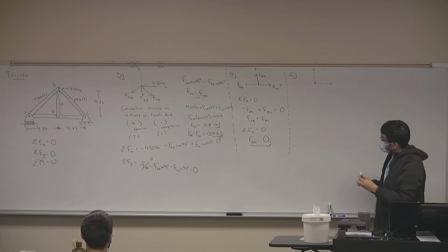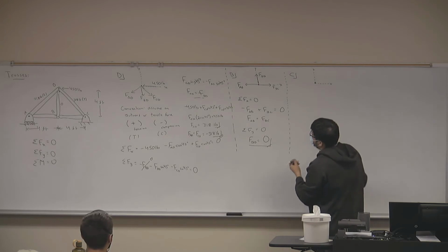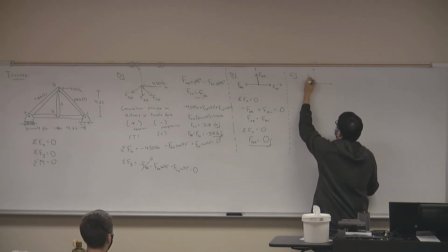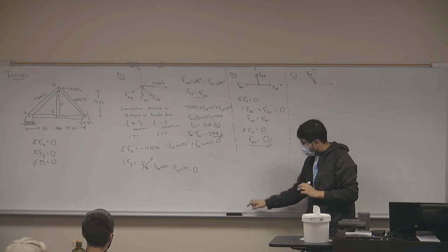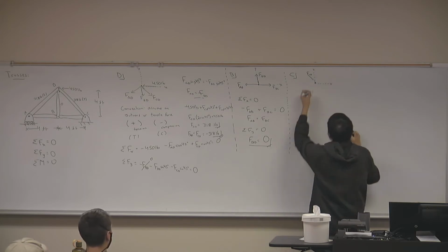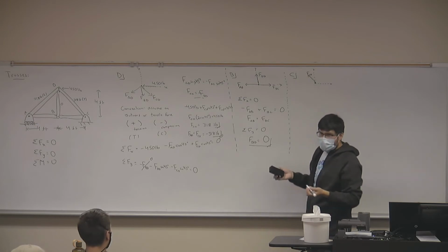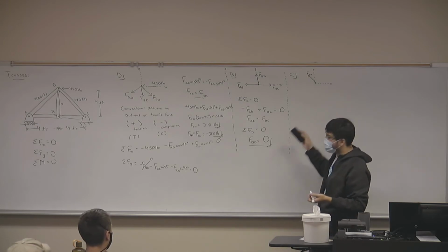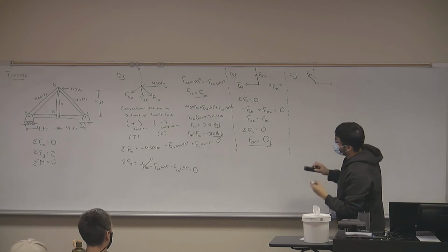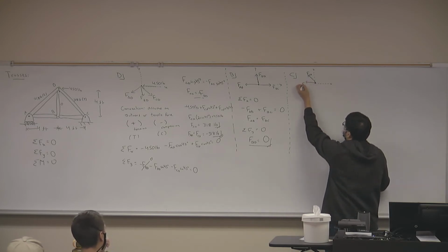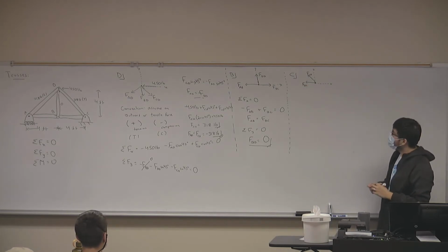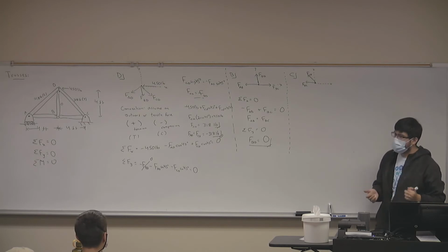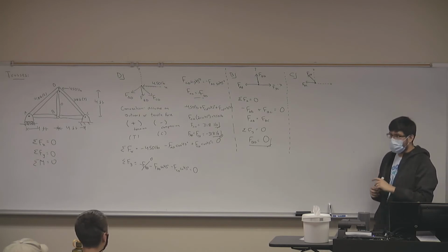FCD and FBC. Okay, so FCD in this direction, right? Is it in this direction? No. Okay, there we go. One, we know it's tension, but two, just by convention, we will set it as a tensile force. And then we have FBC, right? Now, from what you know from statics, are these the only 2 forces? No. What are we missing? The normal forces too. There we go.